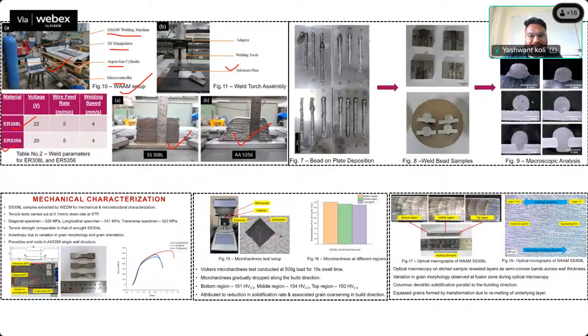So how has he reached this? Because we have to optimize the weld bead. So he has done the optimization of weld bead also. Micrographs, we have taken of the processes. Then only this best combination has been made. So you can see there is no staircase defect, and the humps are also not there. You can see it is a very good single wall structure. So it is not fabricated by hit and trial method. We have to optimize the weld bead. Then only we can get the best process parameters to get this final product.